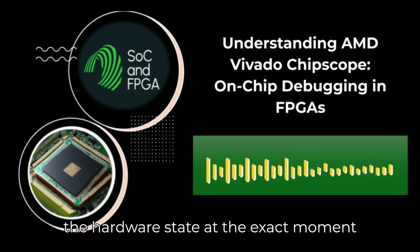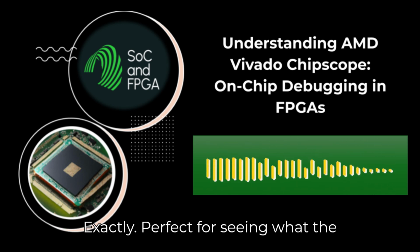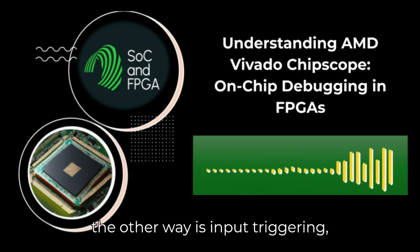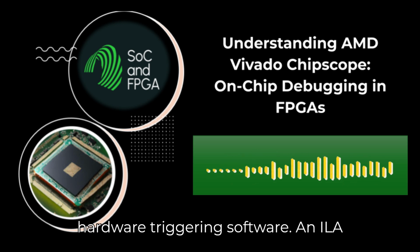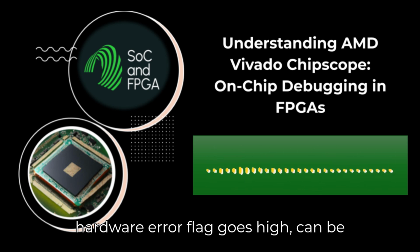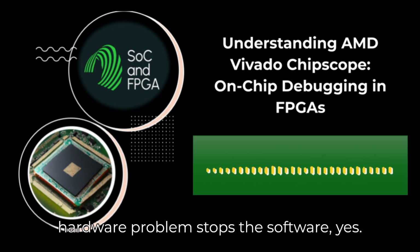So you capture the hardware state at the exact moment the software hits a certain point. Exactly. Perfect for seeing what the hardware was doing when the software did something specific. And the other way? The other way is input triggering, hardware triggering software. An ILA trigger event in the hardware, maybe a hardware error flag goes high, can be configured to halt the processor. So the hardware problem stops the software.